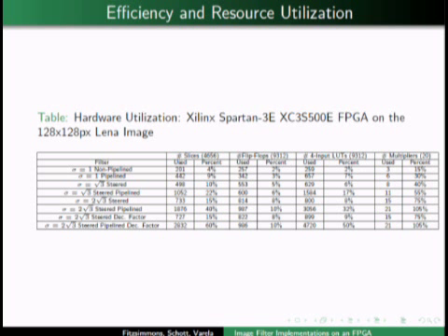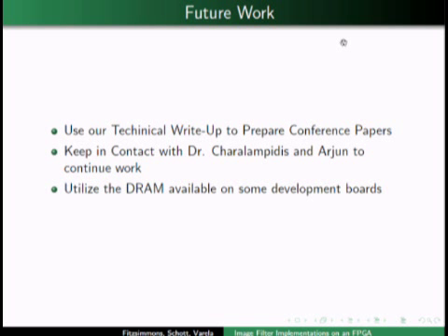So for example, in the non-pipelined implementation, you're doing roughly 15 multiplications per cycle. Yeah, you're doing more like 21 per cycle in the pipelined implementation. And another thing is that rather than doing 32 additions in this case per cycle, you're doing 47 in this one. So you're doing a lot more operations at once, which is why the logic increases, but it's worth it for the execution time.